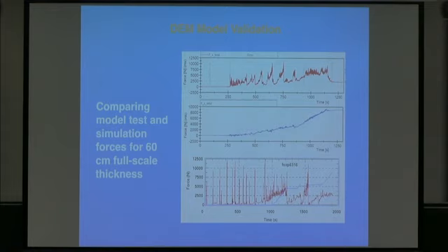Yeah. But that brings up a good point. Suppose you want to match the modulus. In this 2D model, if we crank the modulus up to 1 or 2 gigapascals, we get brittle behavior, and it just doesn't look real. So we have to artificially dial the modulus down to 100 megapascals in order to get non-brittle failure. So that's the one big shortcoming or allowance that we have to make for the numerical model. I'll mention that again later.